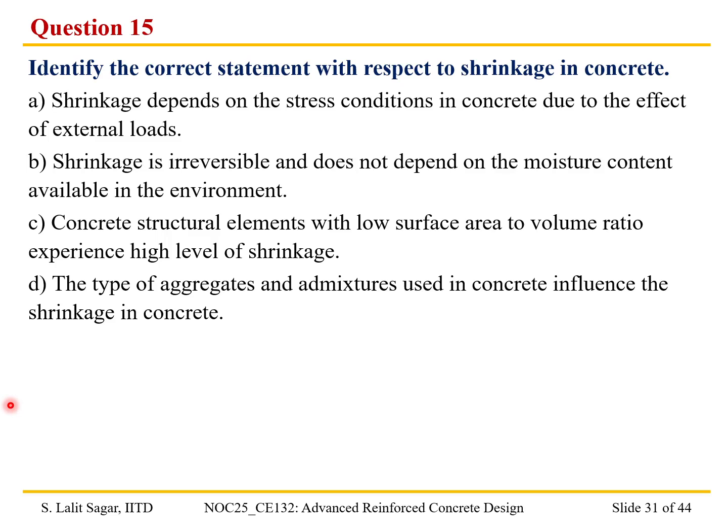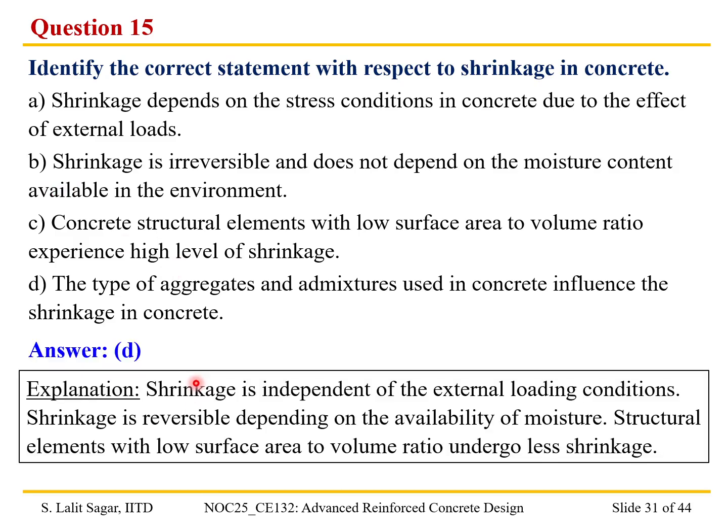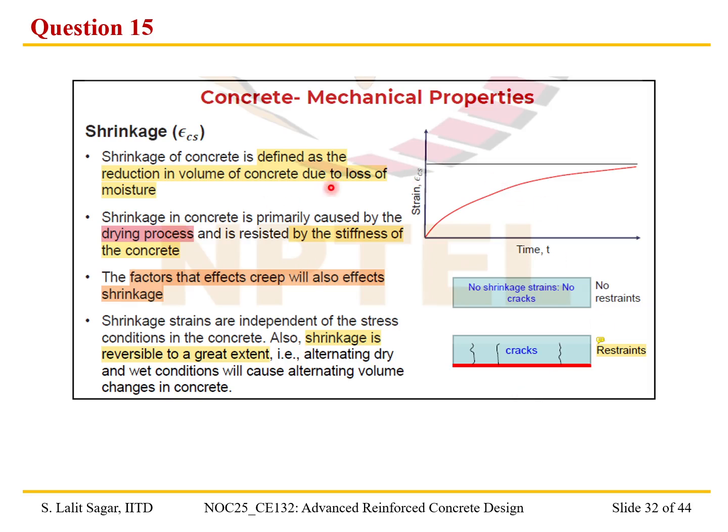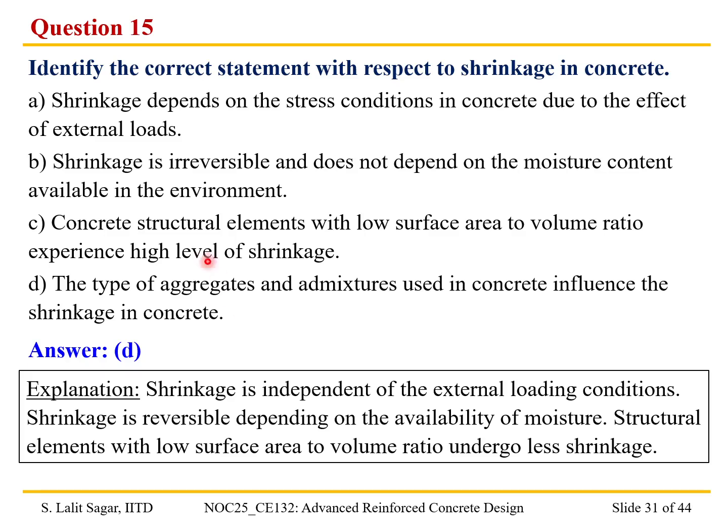So out of these statements, which one is the correct statement? Option D is the correct statement. Let us look at the reasons. Shrinkage is independent of the external loading conditions, as we can see from the lecture slides over here. It is independent of the stress conditions due to external loads. Shrinkage is indeed reversible and it depends on the moisture content.